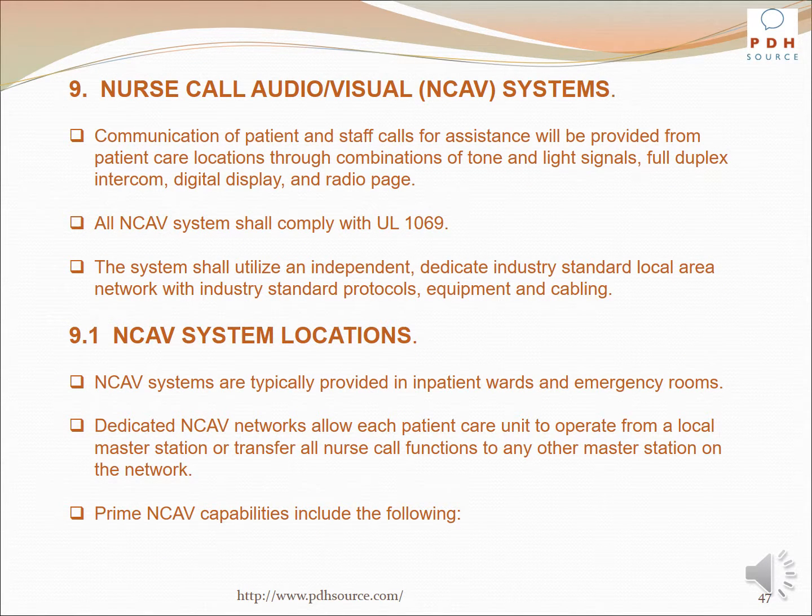Now, with regard to the nurse call audio-visual NCAV systems. Communication of patient and staff calls for assistance will be provided from patient care locations through combinations of tone and light signals, full duplex intercom, digital display, and radio page. All NCAV systems shall comply with UL 1069. The system shall utilize an independent, dedicated industry standard local area network with industry standard protocols, equipment, and cabling.